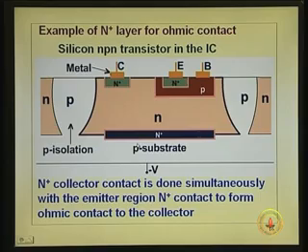If you reverse bias the P n junction, each island is isolated by the reverse bias junction. That is called P n junction isolation, which is very popular in bipolar ICs. Not very high performance, but moderate performance ICs. Because in very high performance ICs, you must put a dielectric layer there, because P n junction isolation may not